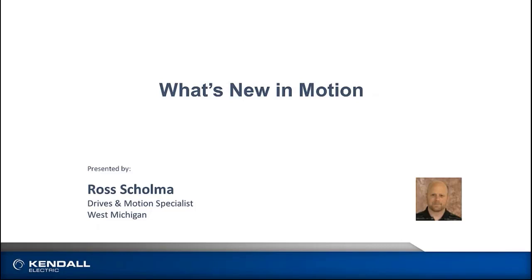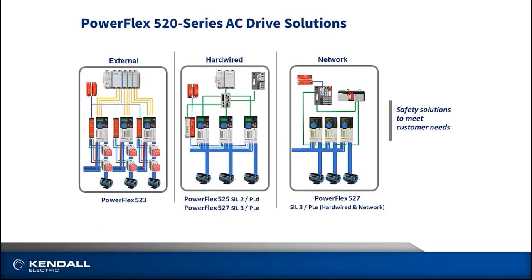To really understand what we're talking about, we kind of have to start with what is safety on a drive system. Typically, we look at it: if we hit a safety input or an e-stop button, what do we want to do? Historically, we used contactors to disconnect the motor from the drive so that the motor couldn't spin while we're in the machine working on it during an e-stop.